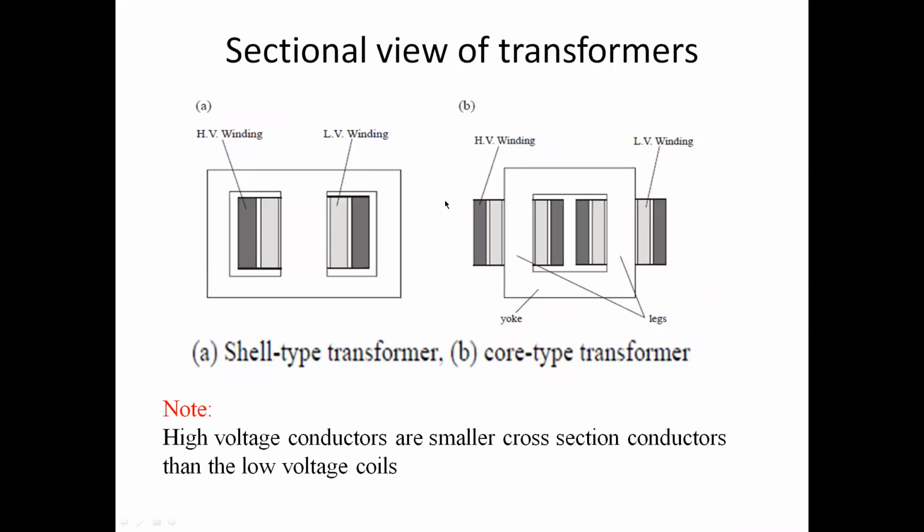We prefer to install the tap changer on tappings provided on the HV, because HV has a large number of turns compared to LV, so we can easily provide a number of tappings. Tapping means we take a connection, so if your HV is outside, it is easily accessible.